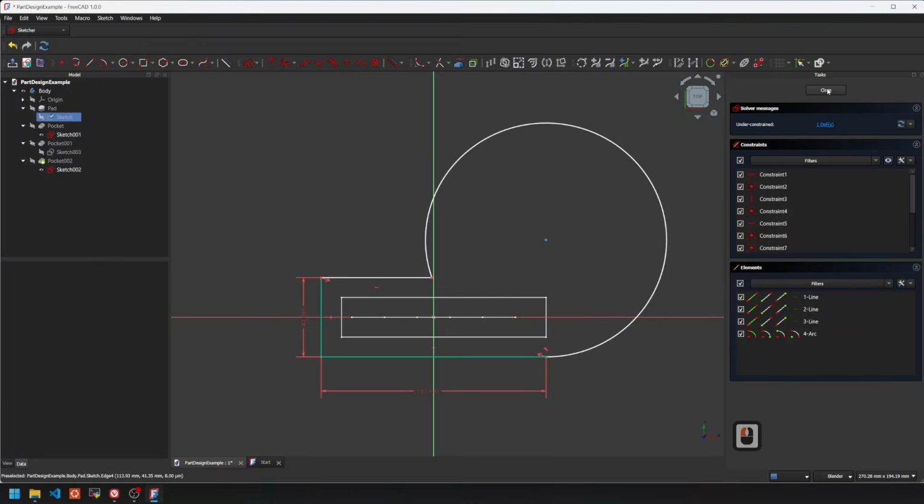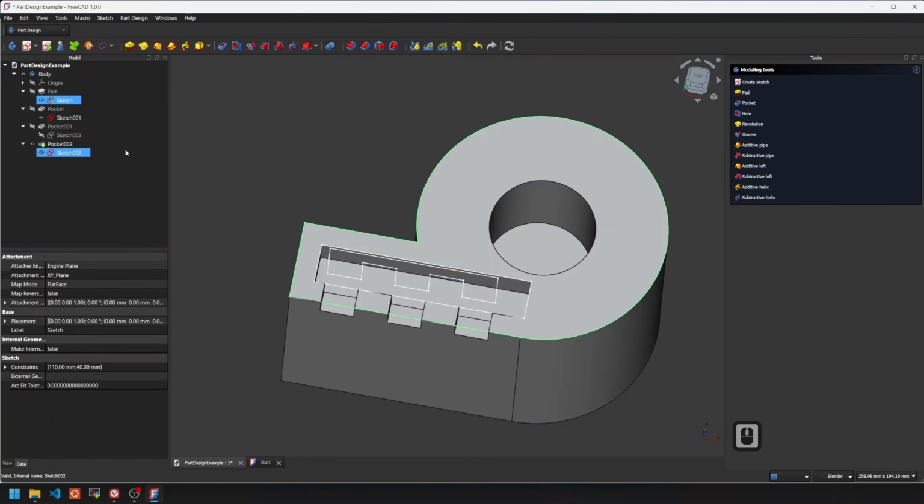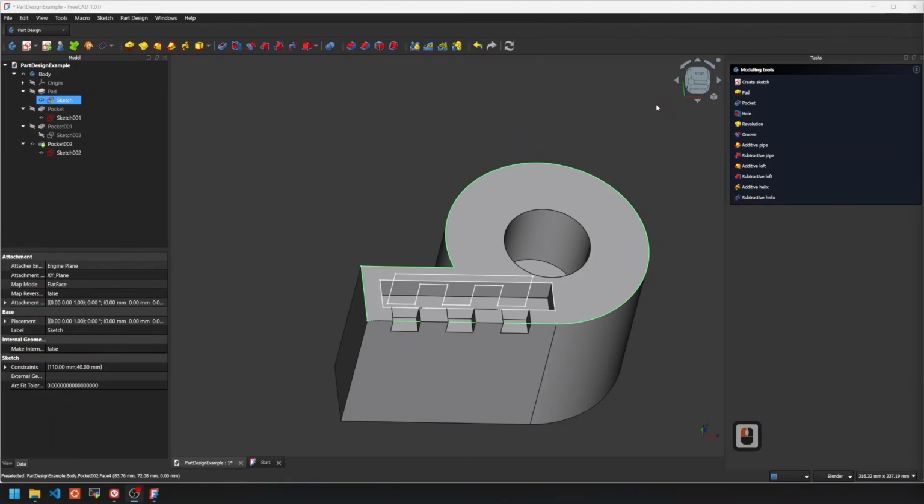Now I click on close here. The changes of my sketch have also been updating the entire model. One thing to keep in mind if you're doing some changes to previous steps in your hierarchy is to keep them as simple as possible. And by that I mean focus your changes on the adjustment of parameters like the length of a side or the diameter of a sphere. You can also do some small adjustments to the shape of your sketch. Otherwise, there's a high chance your model can break, and that's because of the topological renaming issue.